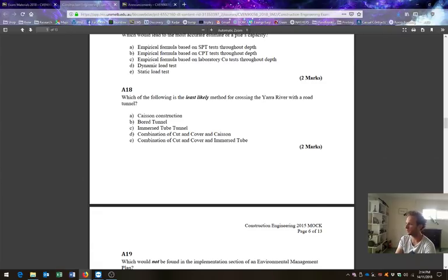I see. So Harry, you're asking about construction method. Okay, so as soon as we're doing an arch, we can't really incrementally launch it. It's not appropriate. So coming back to your previous question, we'd have to use a balanced cantilever construction method for the arch, or a more innovative method like Jeff talked about on one of the bridges in Sydney, where they sort of constructed a temporary arch.